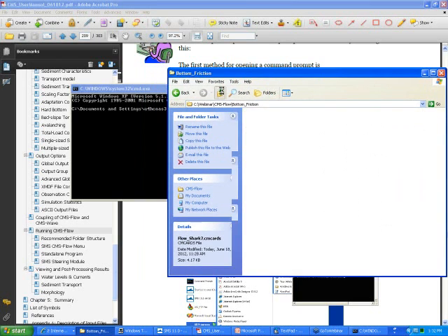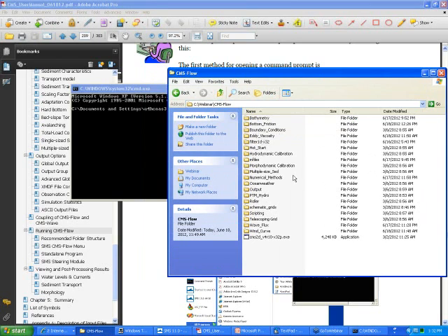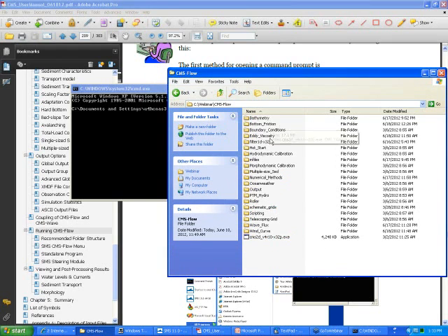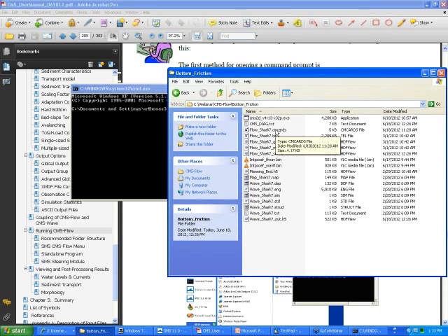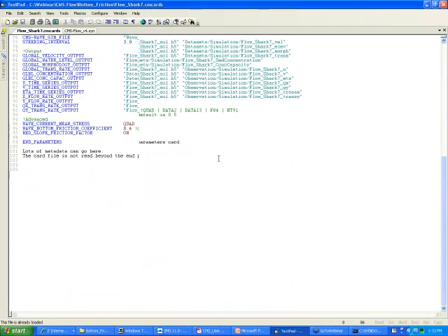And the workshop material that I pointed you to that's on the website has a folder that has all of these subfolders, okay? Bathymetry, bottom friction, and so forth. And each folder is designed for you to have an example of how to change the cards or input parameters for that specific topic. For example, if you're interested in modifying bottom friction, you can go to the bottom friction folder and see how it's set up in there and modify that one. Okay.